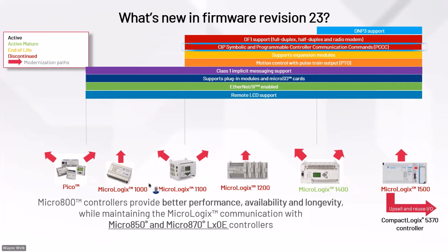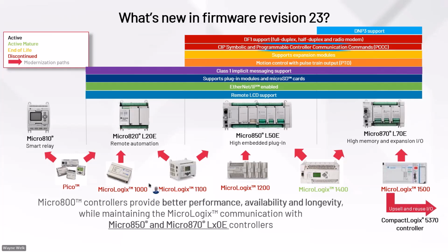This is something I've already addressed, and this is actually a slide that I used back in January. I just want to reinforce that MicroLogix are going away with the exception of the 1400, and I can't really tell you what the lifespan on that is going to be, but I would not want to use MicroLogix as a new system right now. But our migration paths for MicroLogix are generally going to be either a Micro800 type controller or a CompactLogix. So we do have tools in place to help with these migrations.